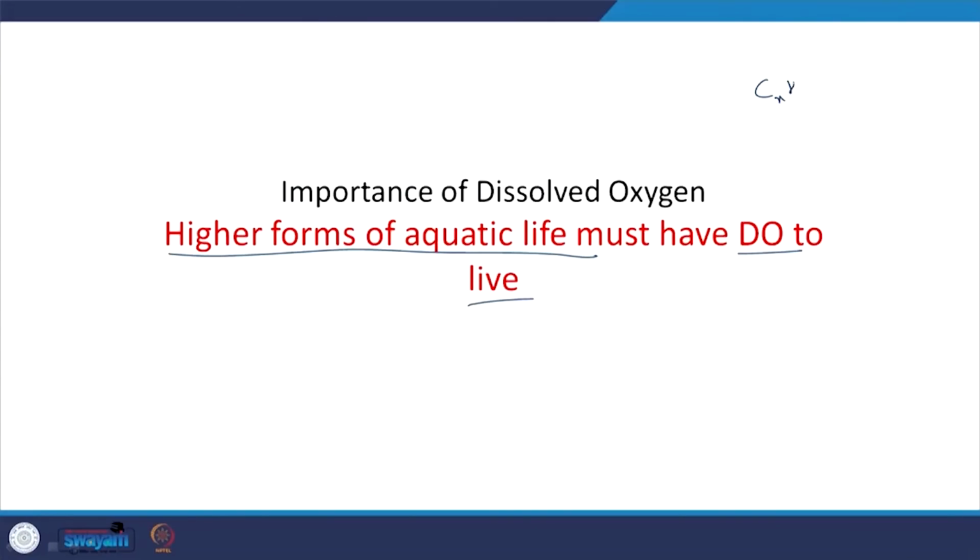So, how is dissolved oxygen going to be affected or decreased? One is if a DO-less stream comes into play, or if I have a lot of organics, C6H, let us say a simple representation of human waste, right. I ate something and I let it out, and if I let it out into nature, what is going to happen? It is going to take up oxygen and go to, let us say, CO2 and H2O or different byproducts. So, we are using up the dissolved oxygen in the aqueous phase, and thus we are creating anaerobic conditions, or no oxygen conditions, in our environment, which is unhealthy. That is something to keep in mind.